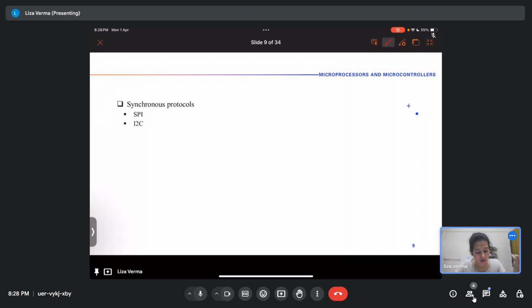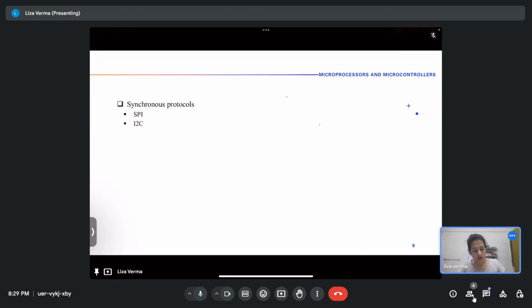Because of master out, slave in, and master in, slave out, you have two connections through which you can simultaneously transfer or receive data. Which, if you will remember, is the definition of a full duplex system.